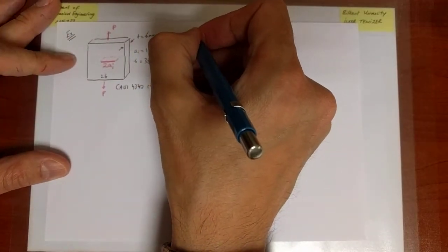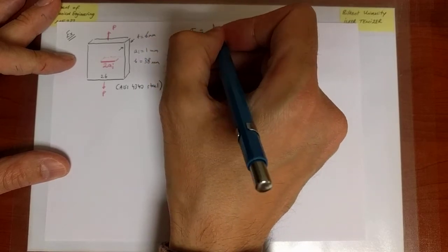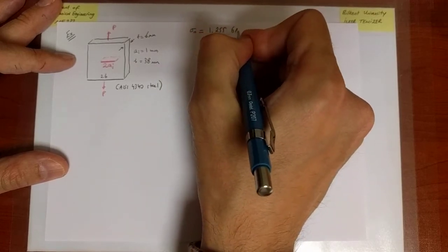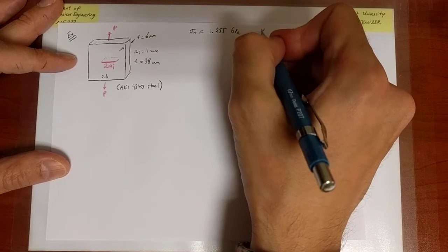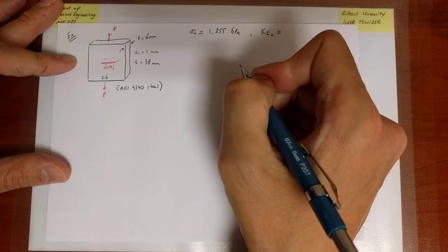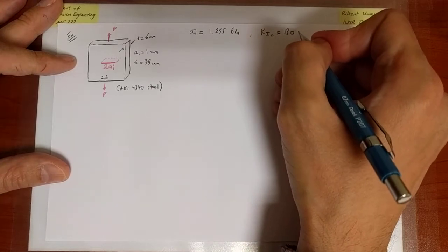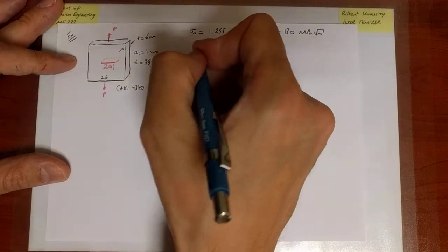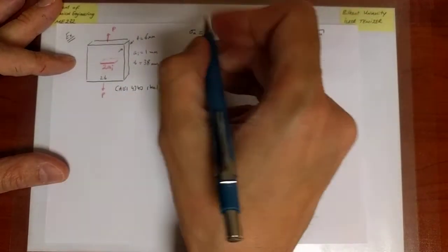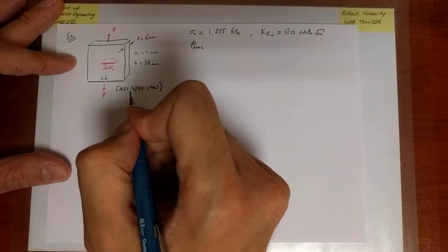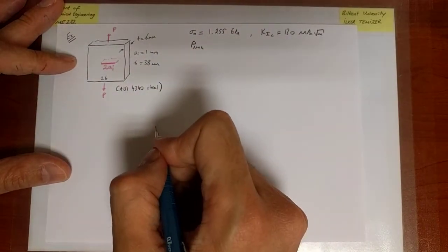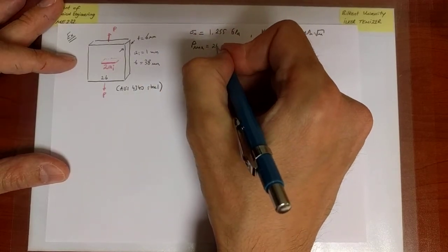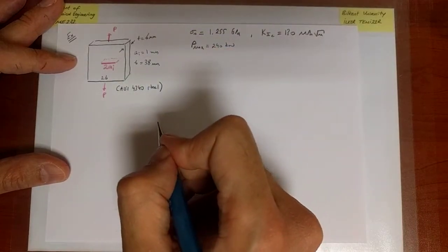So in particular, the yield strength of AISI 4340 steel is quite high. The fracture toughness, let me just write K_1 there. It is mode 1. I don't have to. We've only considered mode 1 so far. Of course, cracks do not grow only in mode 1, but that's what we've looked at as a special case. Remember, we're choosing a path through the complications of mechanics of materials in the context of this course to give you a glimpse into various critical topics. So we have to make a choice at some point, and here we've only looked at mode 1.